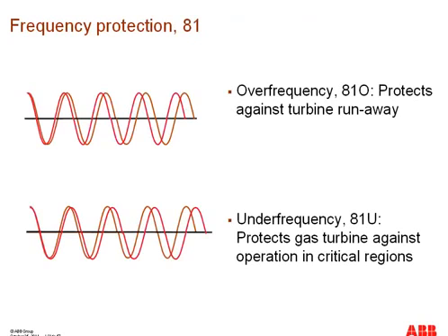Yet another protection provided in generators is the frequency protection. Over-frequency conditions will occur in the event of sudden rejection of load. Sometimes governor problems can also cause over-frequency conditions. This function can be used for generator shedding as well as remedial action. If the frequency remains above the set value for a settable time, then a trip is issued. And this function is normally supervised by an under voltage function.